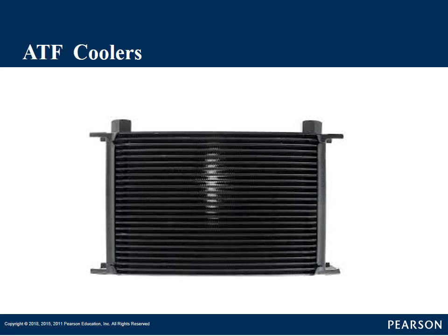Matter of fact, when I recommend people, if they want to put transmission coolers on, I don't even recommend tube and fin coolers, because they're only really efficient on a moderate level, and for the most part, if you're not really doing any towing or hard driving, you don't need an external cooler.